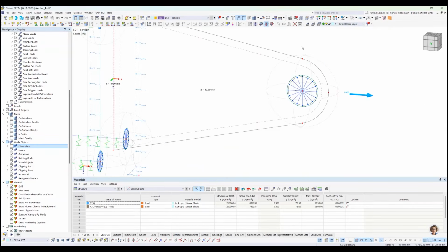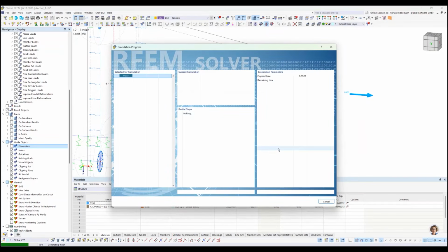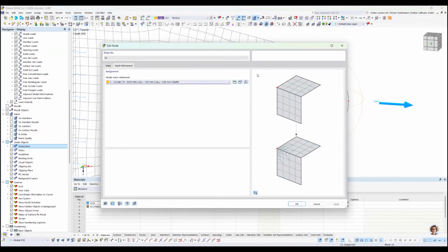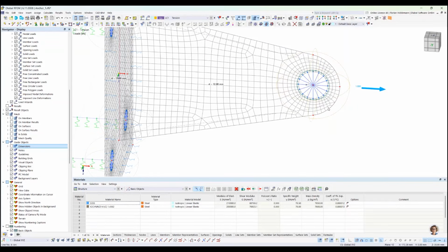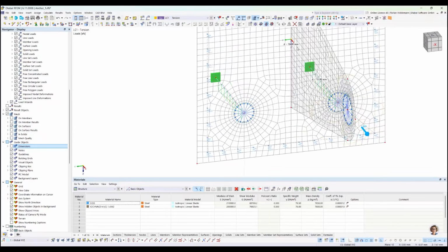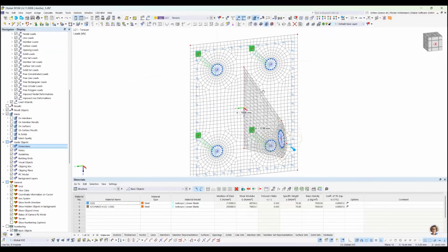Around the structure, there is a mesh refinement. So we would like to see a finer and nicer mesh in this area. Here is a radial node mesh refinement defined, circular. And even if this is bigger than the connecting plate, you can see that we have a nice structure for the mesh. On the plates itself, there are also defined some mesh refinements which make smaller elements, just to ensure that we have a good looking, well distributed fine net here.